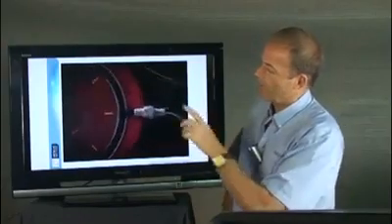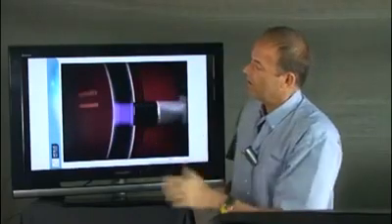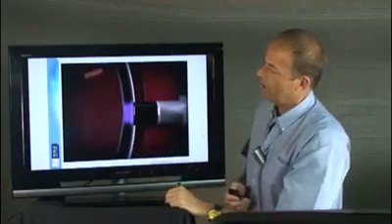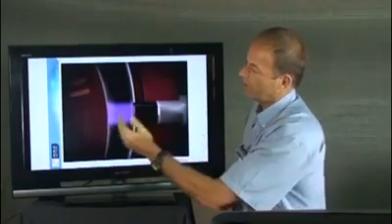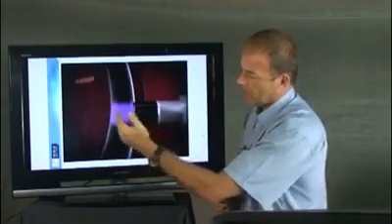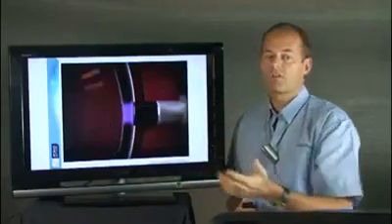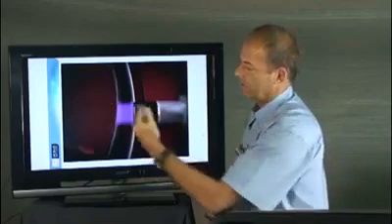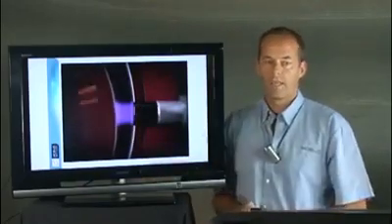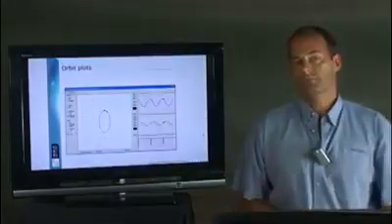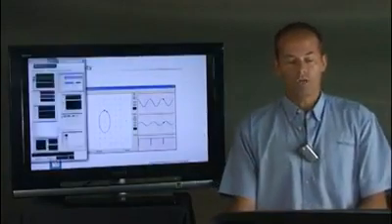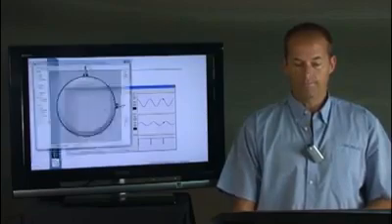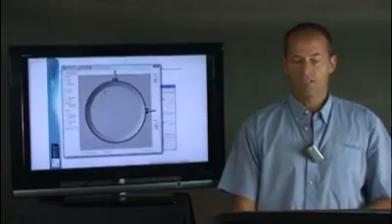The probe can tell us just what the distance is between the tip and the shaft, and then if the shaft is moving we can get that vibration change. We'll get a differing voltage signal as that shaft is moving back and forth like that, and it's that motion we are interested in. So without further ado, I'm going to bring up my orbit simulator, and here it is.